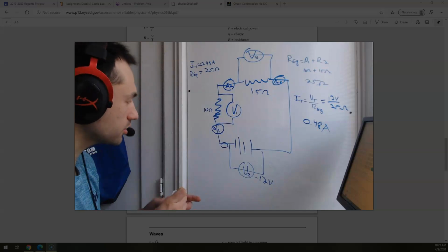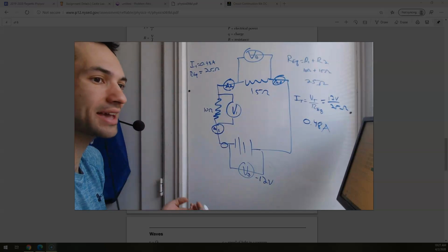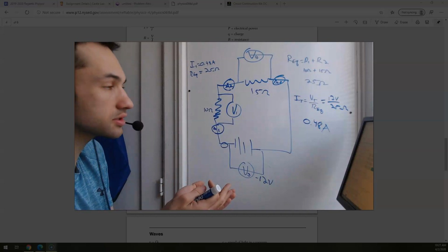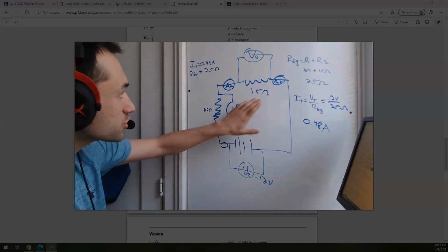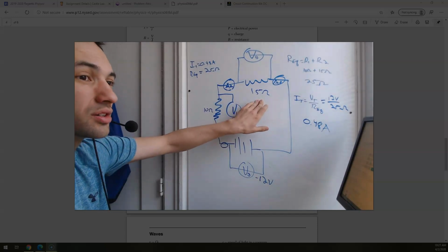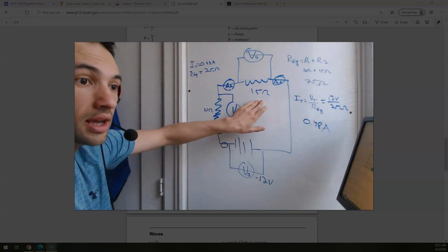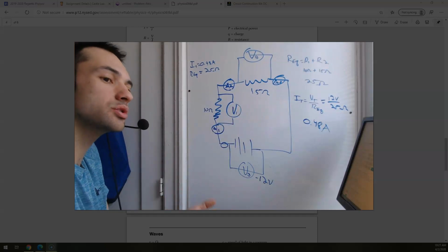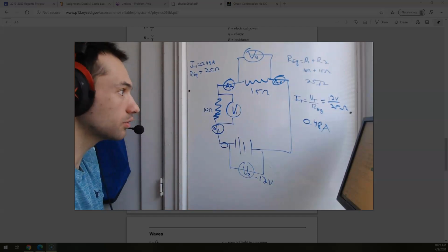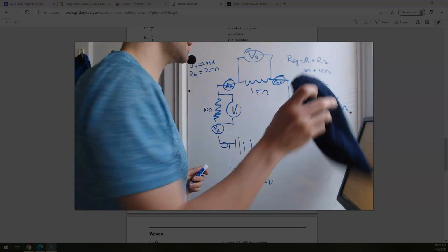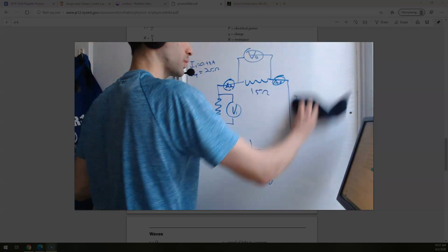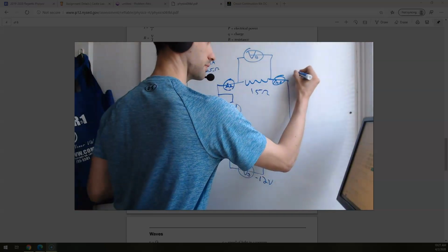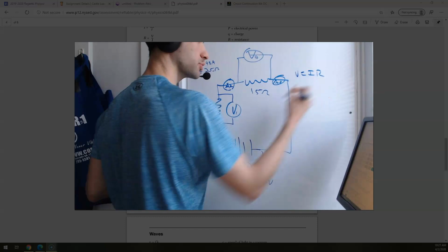So what it has to do as it goes through the circuit is give a little bit of energy to one resistor and then a little bit of energy to the other resistor. This resistor has a higher resistance, so it's harder to get through. If it's harder to get through, we're going to expect more energy needs to be used to get through it. So let's do the calculations and let's find out. Again, this equation is always true as long as we put our subscripts. V equals IR as long as we put our subscripts.